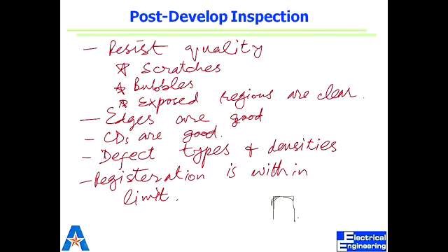Critical dimensions are good. What is critical dimension? Let's revisit again. What is critical dimension? Feature size. Feature size? Yes, of course. Everything has a size and every feature has size, but what is CD? The smallest distance that you can specify without losing the resolution. The smallest feature size you can, in pattern, without losing the resolution for a given technology, right?